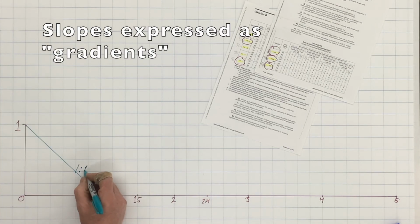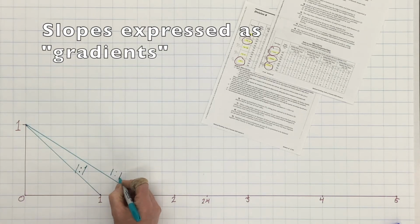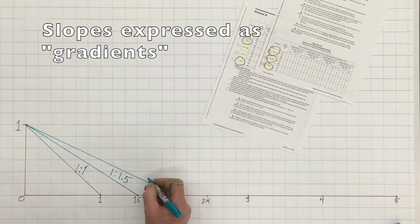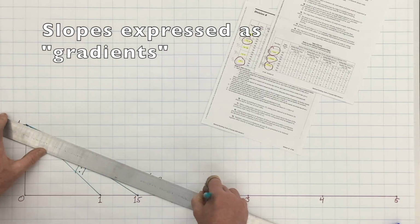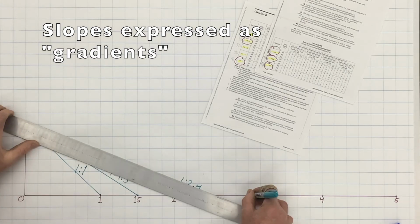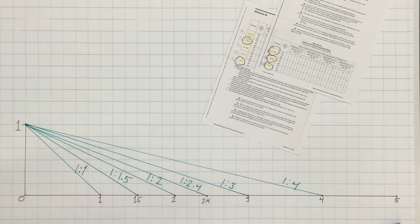1 to 1 has both a rise and run of 1, making it equivalent to 12-12, 100%, 10 to 10, or 45 degrees. 1 to 2 has a rise of 1 and a run of 2, making it equivalent to 6-12, 50%, 5 to 10, or around 26 degrees. 1 to 4 is the same as 3 to 12, 25%, 2.5 to 10, or around 14 degrees.